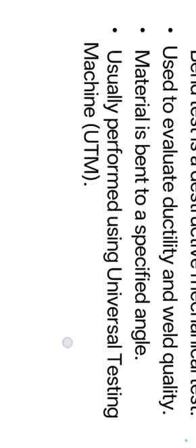Mechanism: the test involves placing the specimen on supports and applying force with the universal testing machine, creating tensile and compressive force from the center. Definition: a bend test is a test in which a specimen is bent to a certain angle theta from the original, to determine its ability to withstand plastic deformation without cracking.